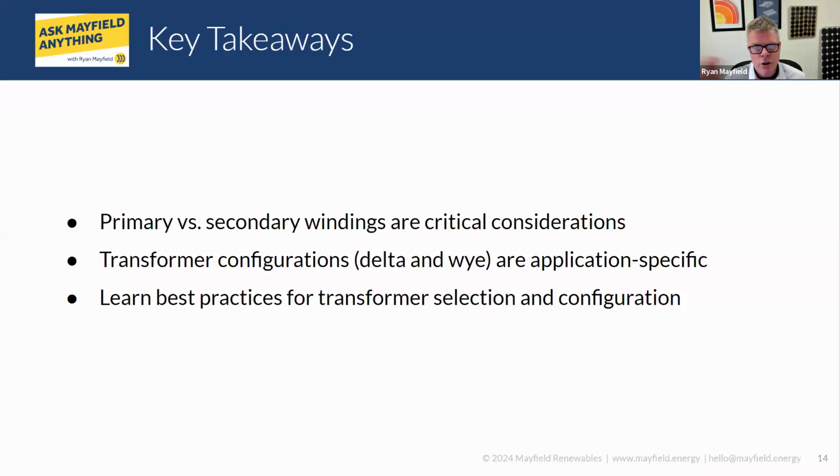Another question that came in, going backwards to towards the beginning, when we were talking about delta Y configurations: do we ever see delta delta configurations given that PV inverter? Again, we're talking about grid direct PV systems, not energy storage at this point. Since a lot of inverters don't require the neutral as an absolute, do we see delta delta?